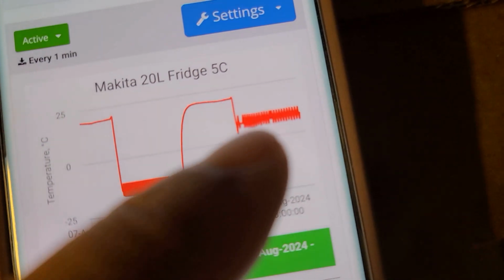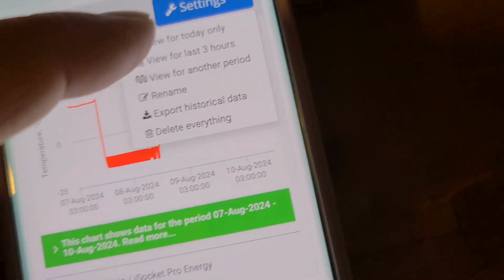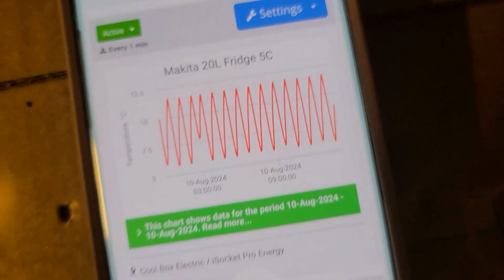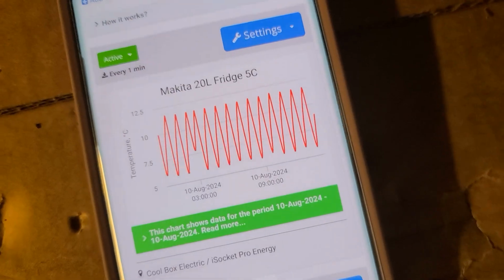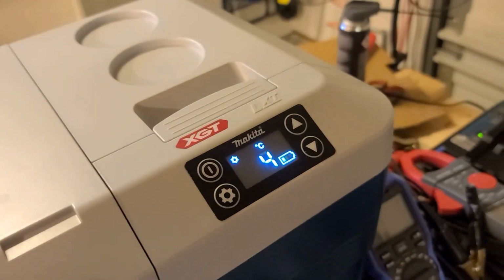But guys, look what I found on the temperature profile. I see it again has some gap there. And if I watch for just 1 day, I see this gap, and I clearly realize what that is. That is exactly the moment when it switched from the first to the second battery. That is awesome. So, for example, in case of another fridge, if you see something like that, it means either something with the compressor or with the power supply. In our case, something with the power supply, with the battery that was empty and switched to the second one.